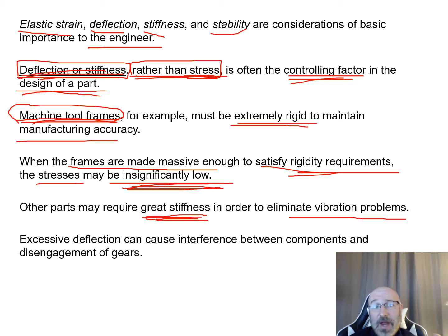It doesn't interact the way it should. A great example of this is gears. If we're talking about gears and all of a sudden one or two of the gears deform, they lock into place because they've expanded too much, and then the whole system doesn't move, it binds. Or maybe the opposite, it contracts a little bit, it shrinks up and moves away from each other, and they don't engage anymore.